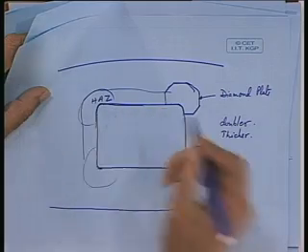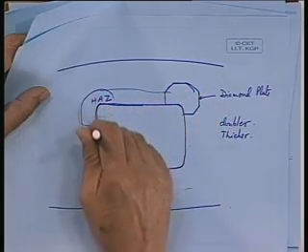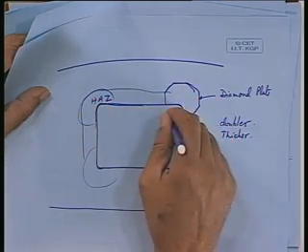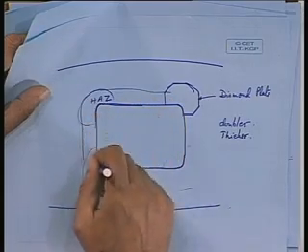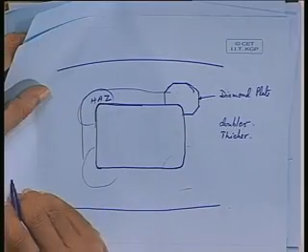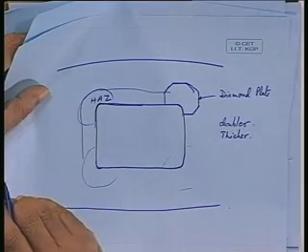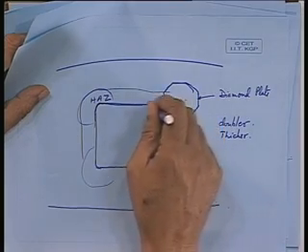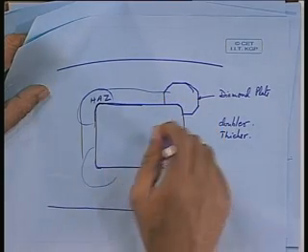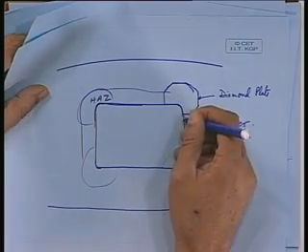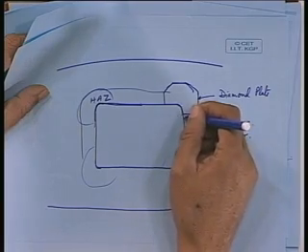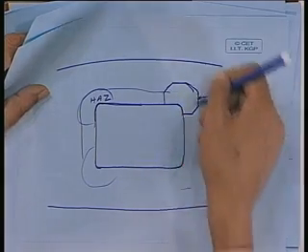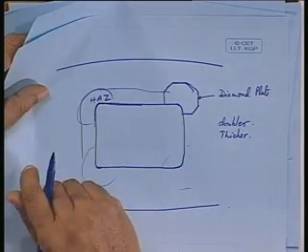After that we try to put some sort of either a doubler and then some sort of a combing. So, when you put a doubler here, you are again heating and cooling, and then when you put a combing here, again you are heating and cooling. Not only that, you will try to weld it from this side, and from underneath also.